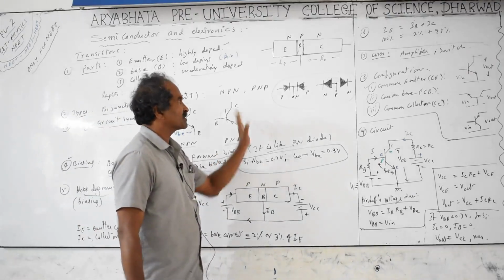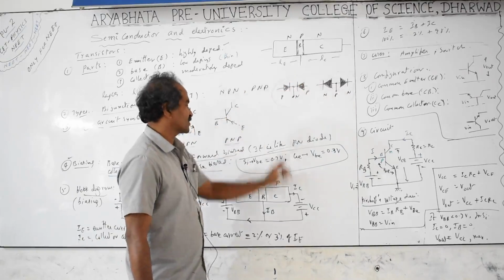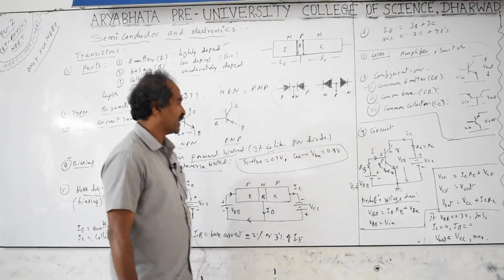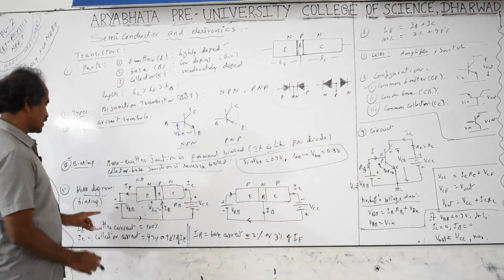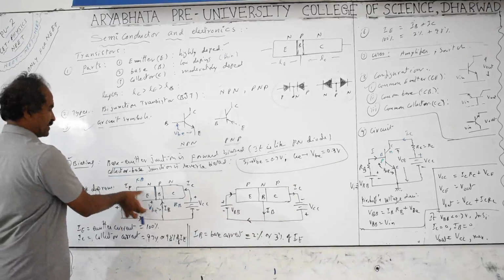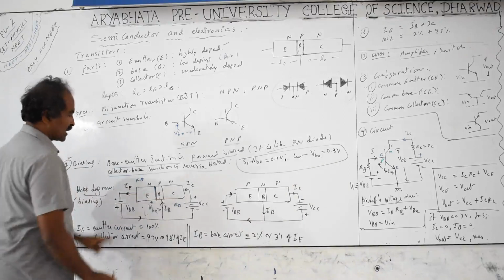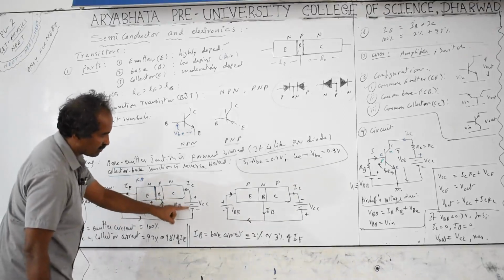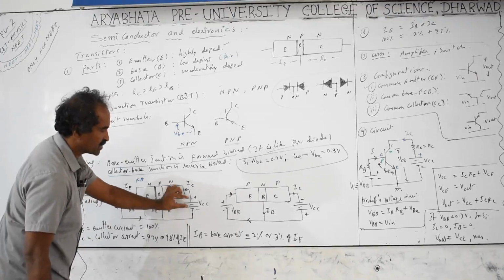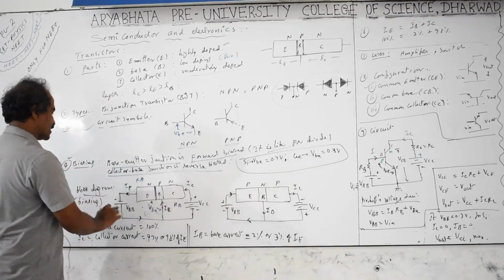For germanium, if the complete transistor is made of whole germanium or whole silicon, and you are using a germanium transistor, VBE is going to be 0.3 volts. So here the battery voltages are connected between the emitter and base, and between the collector and base. For the collector base we take more voltage, a series of batteries. In the diagram I drew two plus-minus symbols, meaning two cells in series, so the voltage is higher than that of VBB.